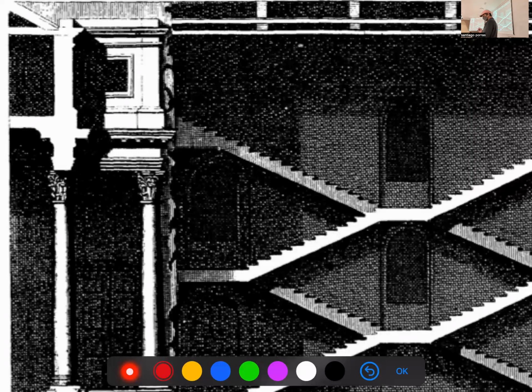One thing that all the classics tell is that a monumental stair has a small angle, right? Usually we have like 30 degrees, the basic comfortable stair. This is much softer. So monumental stairs, the lower you make them, the easier they are to climb, which makes the building more accessible, because accessibility is not only ramps, it's the stairs being usable by other people. But a small slope also makes stairs much more pleasant and monumental in some sense.